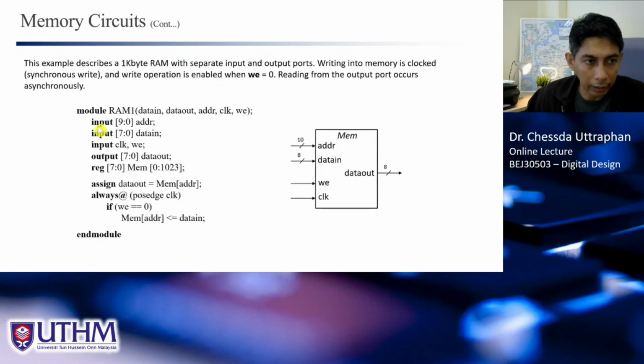So in the declaration, of course, the address is 10 bit, so input [9:0]. Data in is input 8 bit, [7:0].